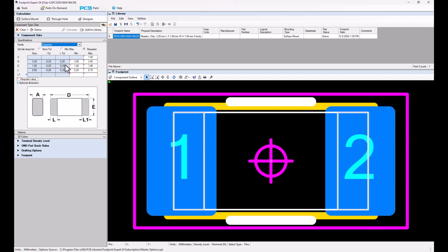So if you want the same package, same footprint, the same pad stacks, same spacing, same everything for an 0603, you would create a master 0603 taking all your sources that you get from Panasonic, AVX, Yageo, Vishay. You might want to take all of your sources and put them all together and find out what all their tolerances are, the positive tolerance, the negative tolerance, and the size of the package.